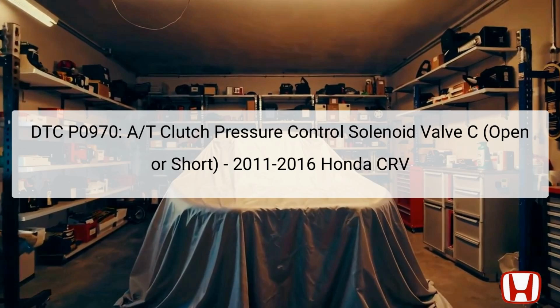The Diagnostic Trouble Code DTC P0970 indicates an issue with the automatic transmission system in the Honda CRV models from 2011 to 2016. This code specifically relates to the AT automatic transmission clutch pressure control solenoid valve C, signaling that there is an open or short circuit within its electrical system. The solenoid plays a crucial role in regulating the transmission fluid pressure to ensure smooth gear transitions. It's typically located on the transmission of the vehicle and is connected to the powertrain control module, PCM.